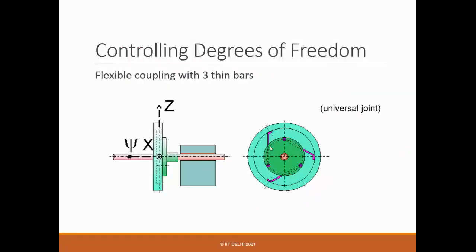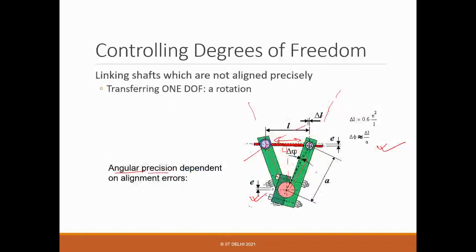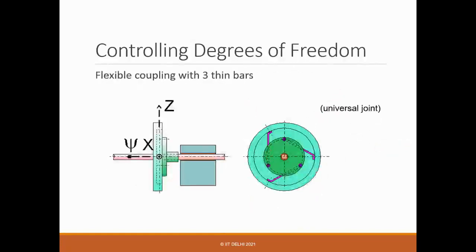So suppose you want to design a flexure coupling, and you want to distribute it, because it may not be dynamically balanced, since it's only offset in one direction. So you can make a very symmetric design here and create a kind of universal joint.